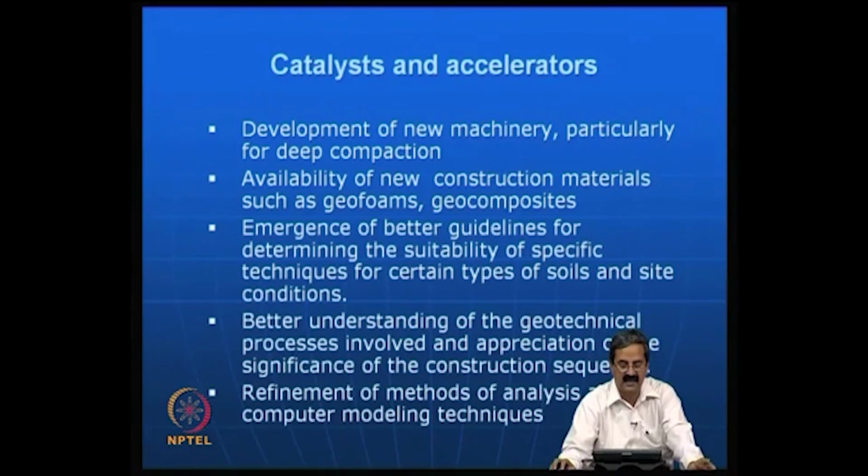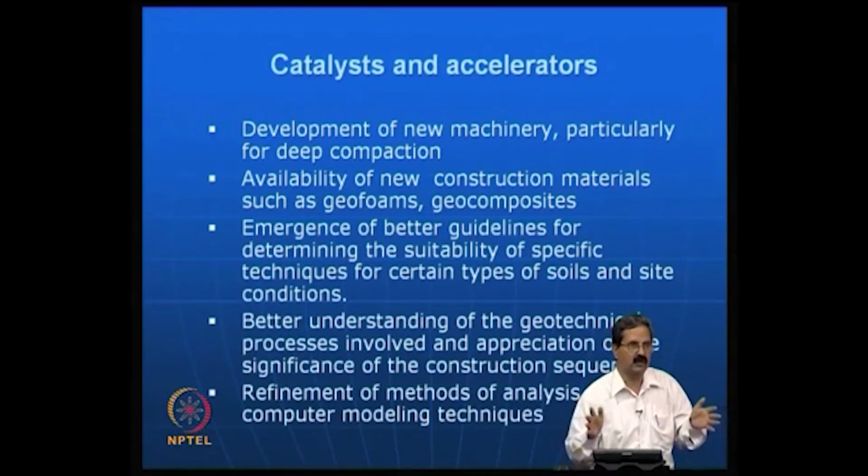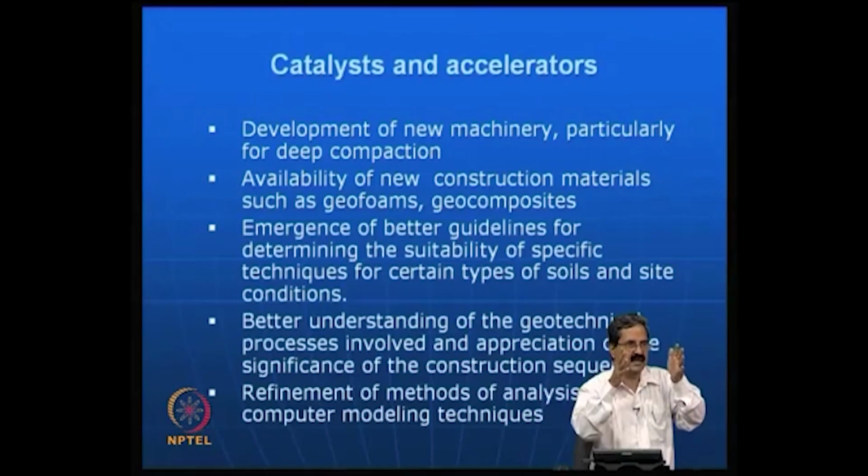And the construction sequence is another important thing, because many of these civil engineering buildings and systems have some construction sequence. I will take the case of a nailing example. Reinforced nailing can be used to construct a retaining wall, like what we have in an underpass. In the conventional technique, you simply excavate completely, say for example 5 meters, then put your concrete and construct the gravity wall.